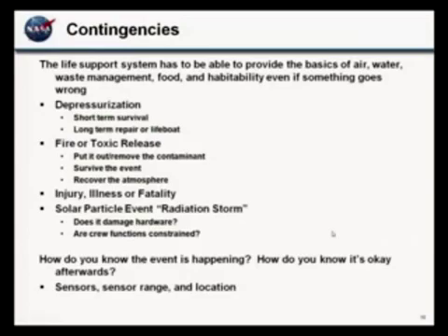Halon does some really nasty things in the high temperature catalytic oxidation beds we typically use. Carbon dioxide is a little better because at least we have carbon dioxide removal systems already, but that's a lot of carbon dioxide you just pumped out. Water vapor, again, we have water removal systems, but that could be a pretty significant load you need to remove to get your habitat back to normal.